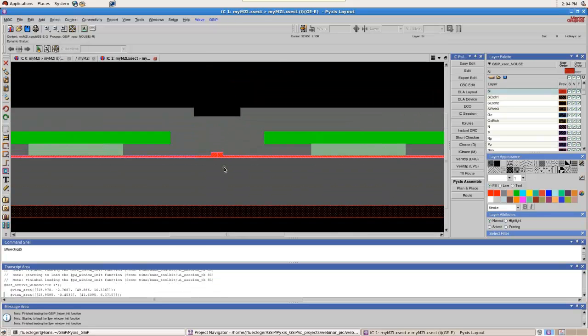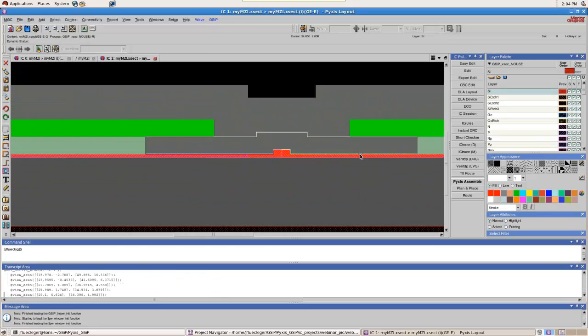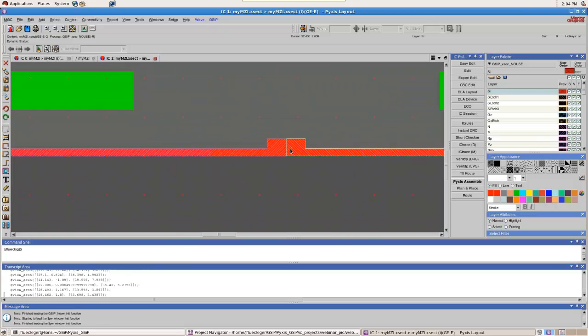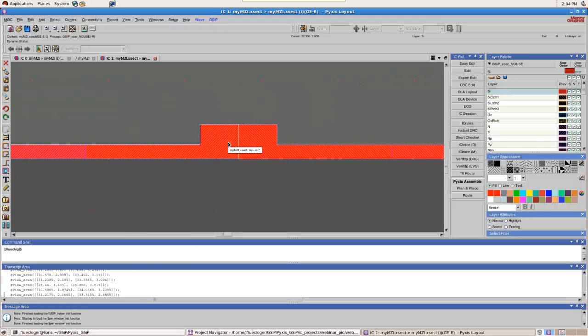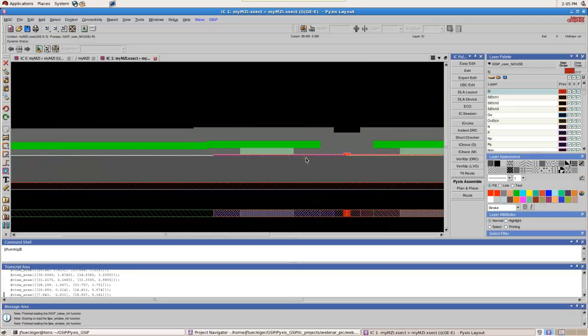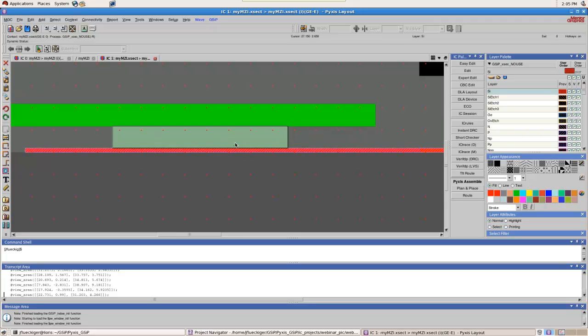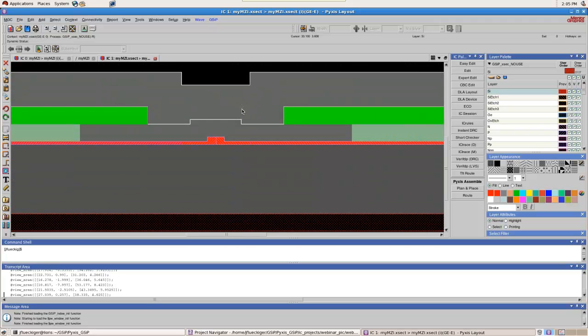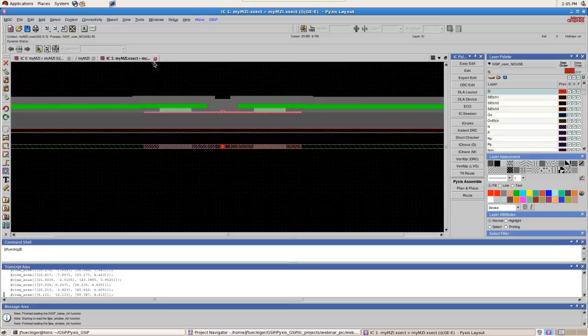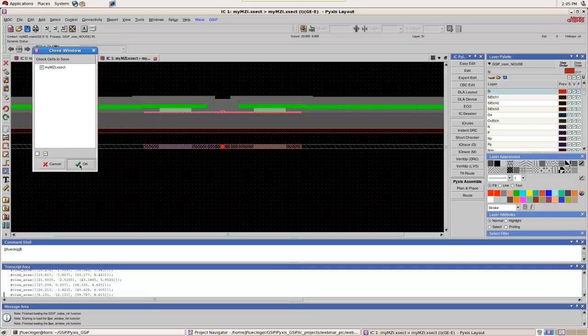So what we have here is basically the waveguide. It's a ridge waveguide with the actual waveguide in the middle. And you can see the p-doped, this is basically the p-doped region. Then we have the p++ doped region, the n-doped, the n++ doped region. So this is all defined here. You can easily see by using this cross-section tool. There's also the via, the contact via. It goes up to the metal layer, and you have the oxide, buried oxide layers. It's a really good tool if you are designing a new device. You want to verify the cross-section. Let me close that.